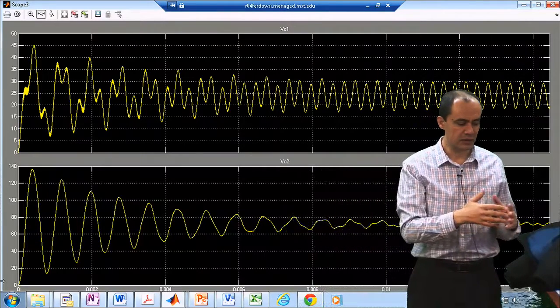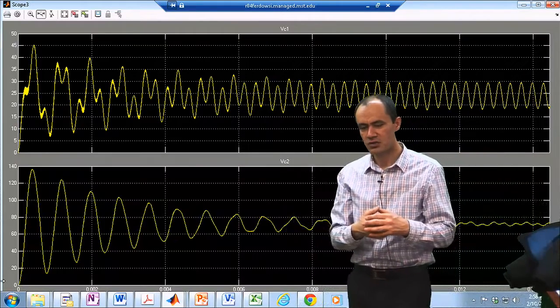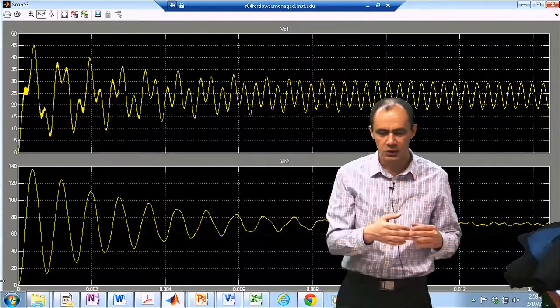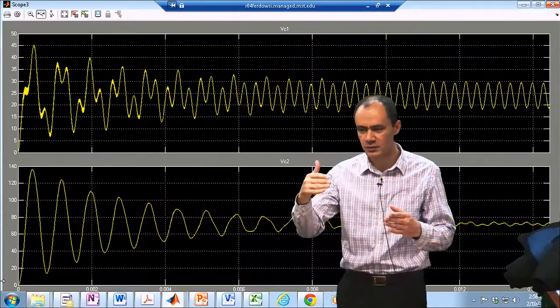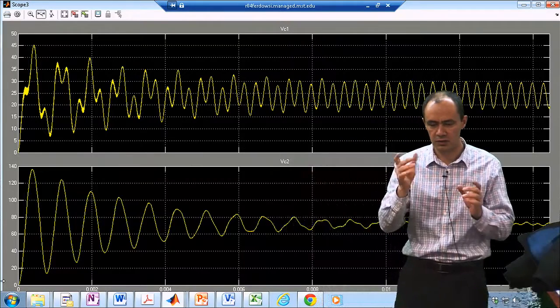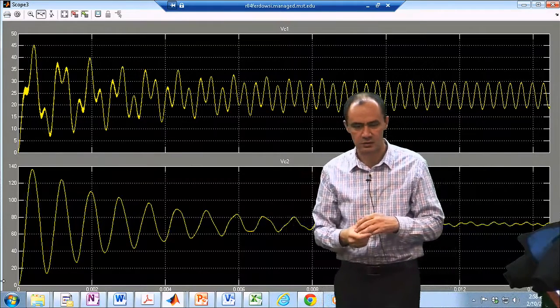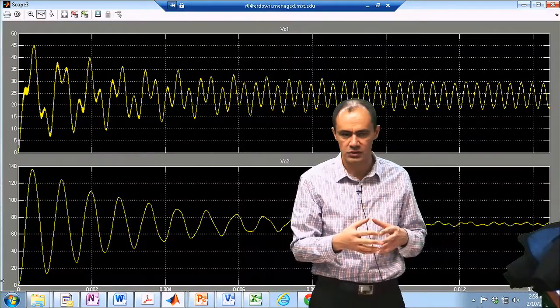But in a real system, you don't have to do that. There is a mechanism called soft start, meaning that you start with a duty cycle of 2%, then gradually increase it to 4%, 8%, then ramp it up all the way to 50% within, I don't know, 5 milliseconds or something like that. If you do it that way, you can eliminate a lot of these transients.